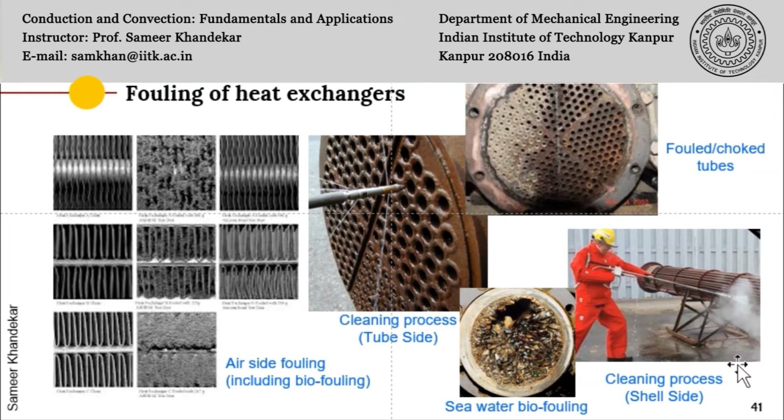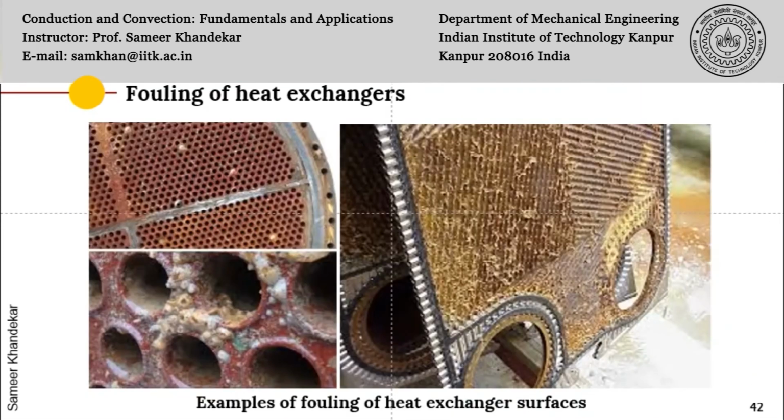And as you can note from these figures, on slide 42 also, some plate heat exchangers, the fouling has been done. Here the entry to the tubes has barnacles or marine deposits. So as you can see, the resistance values which you have chosen for the virgin design may be completely out of sync with the reality over a period of time. And sometimes these deposits can be very fast. In fact, they can just happen over a very quick period of time.